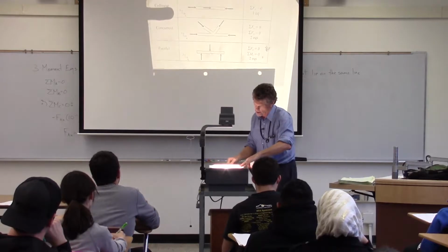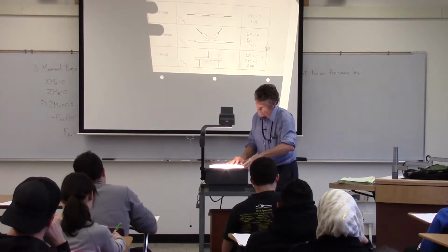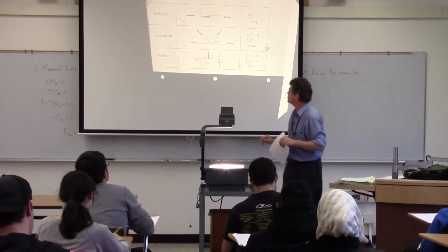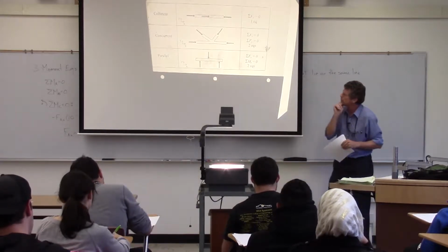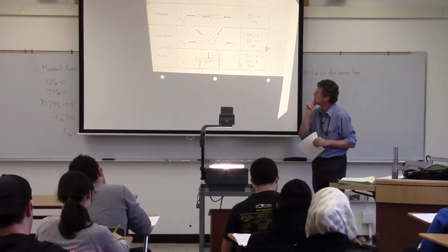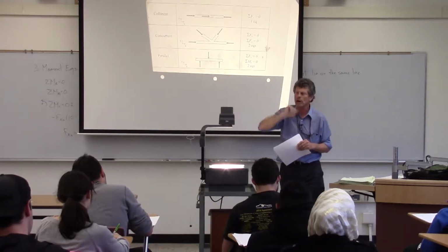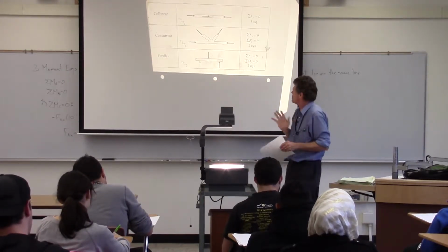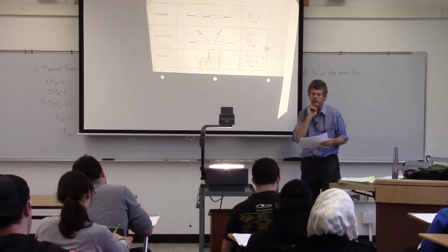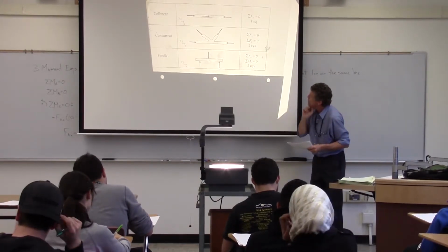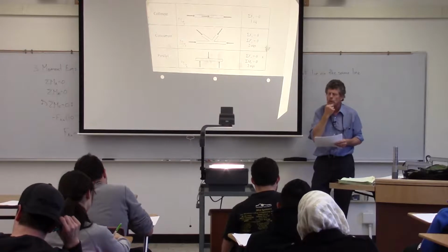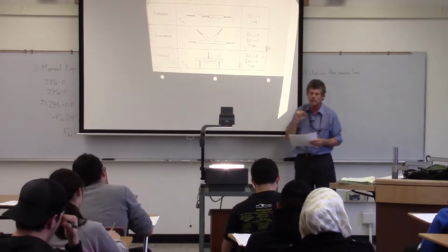Another one that's difficult too, or reduces our number of equilibrium equations, is parallel forces. And again, what we'll find there is that we've got the sum of forces in the y direction, but the sum of forces in the x direction is already equal to 0. There's nothing going on in the x direction there. So in terms of solving for that, we only have 2 equations of equilibrium.